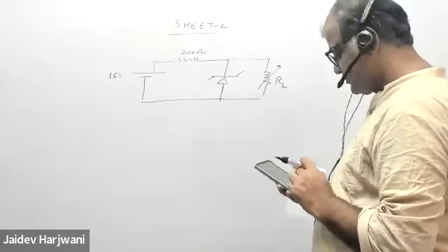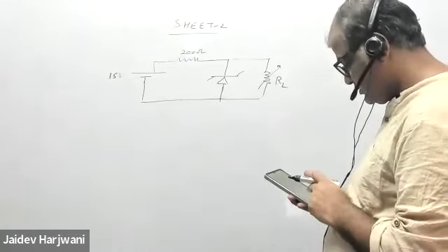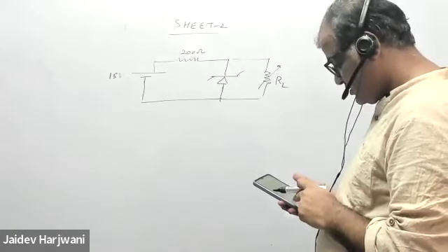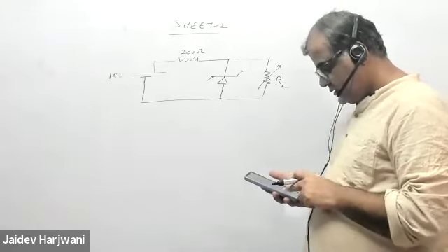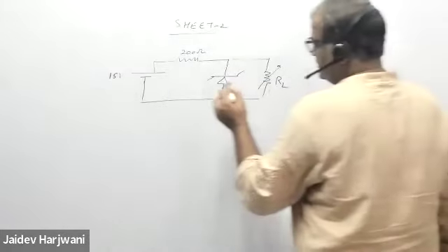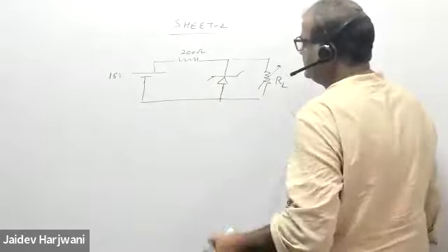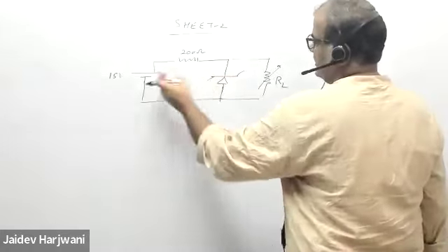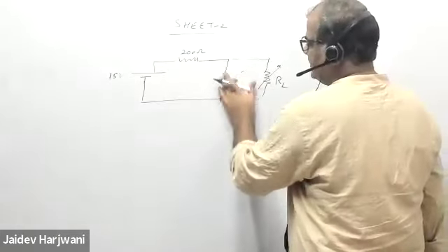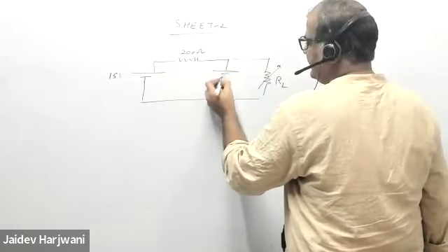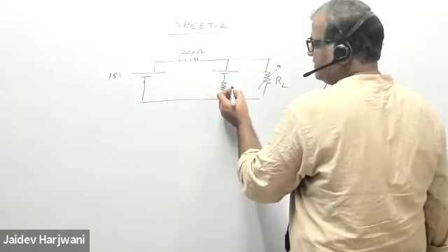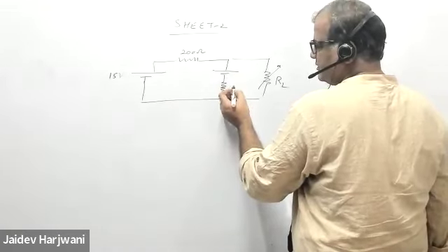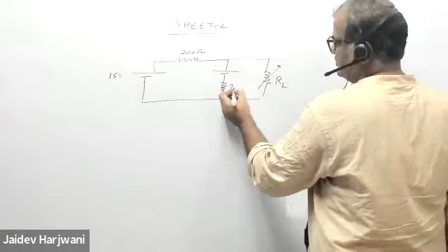So now, first of all, Zener voltage is 5.1 volt. This is required, 5.1 volt. Of course, if I make it open, assuming it is conducting, I can replace it by a battery as well as a resistance. What is the value of resistance? Tell me. 7 ohms. Okay, so this is the value of resistance.